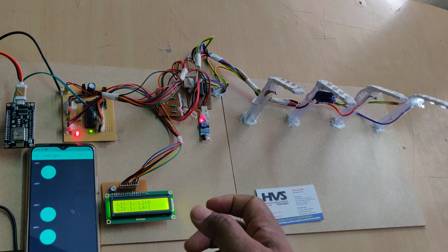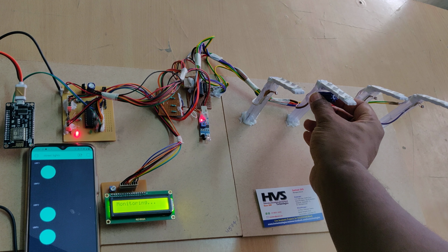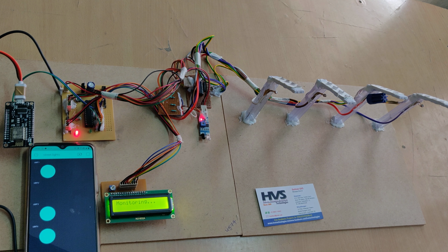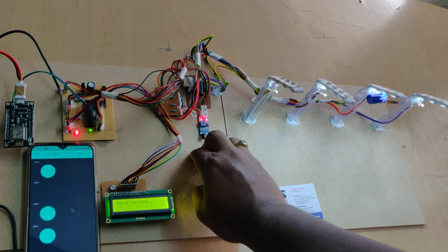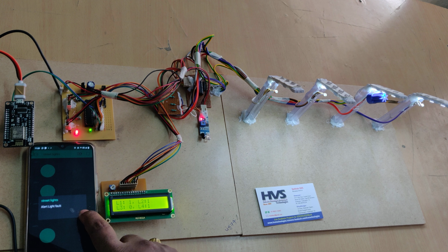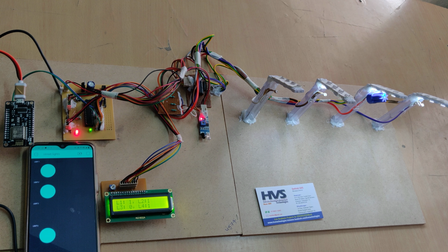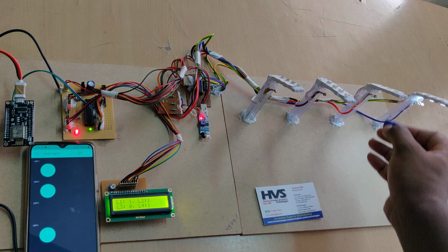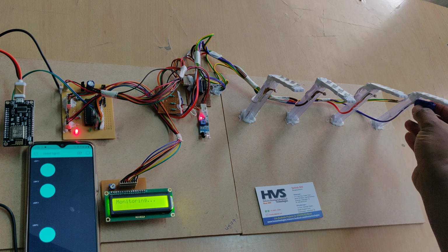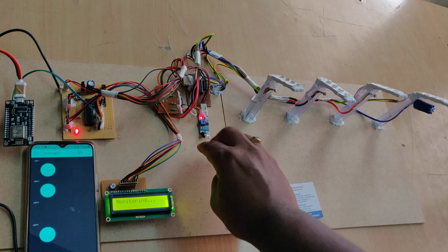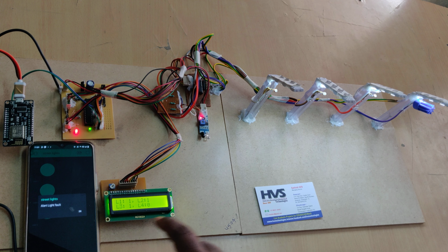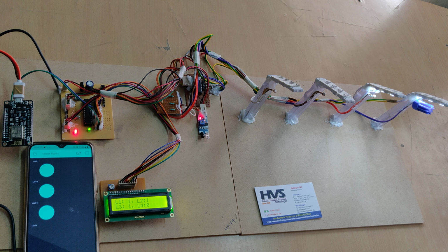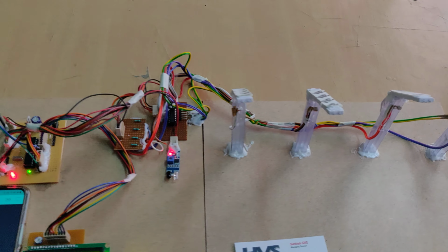Here we communicate the input and output module data from the microcontroller to the Node MCU through serial communication. That's why we convert the data, which is analog or digital, directly to serial. See, one more street light, light 3, is also under fault, and we can see the same thing: 1, 1, 0, 1. And we will do the same for the last street light. We should cover the particular street light properly, or else it will not be detected as a fault.